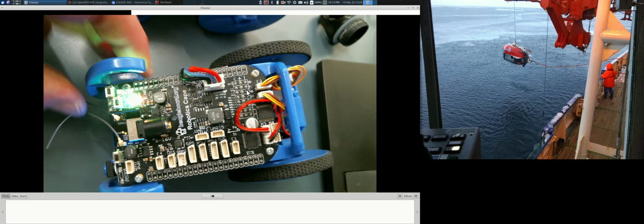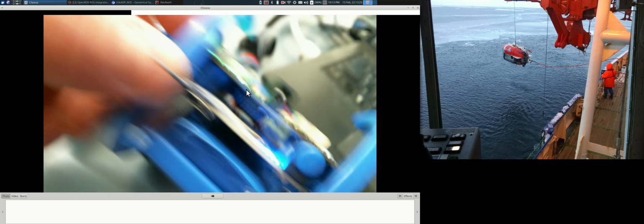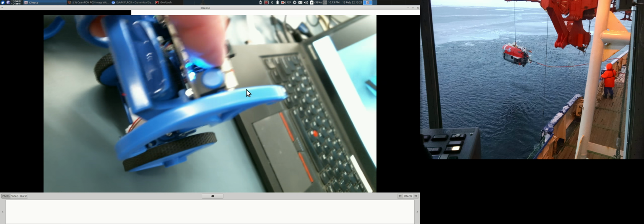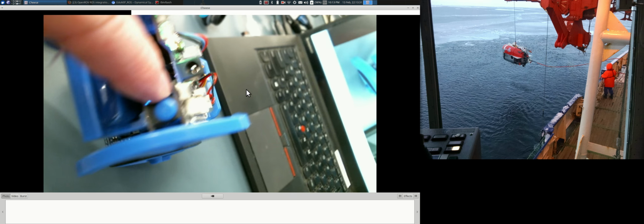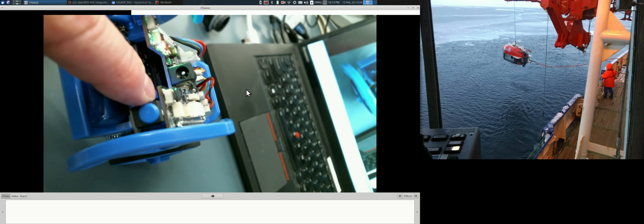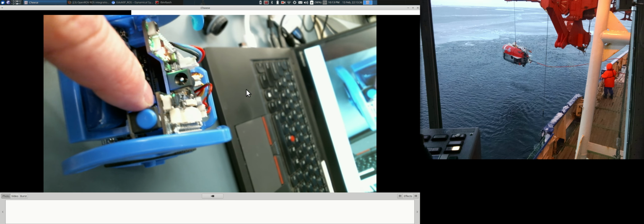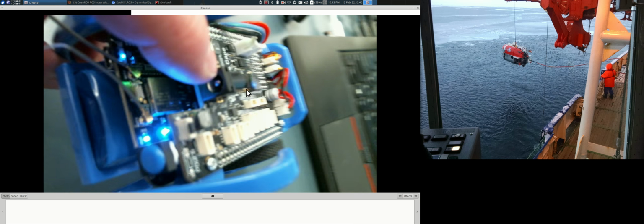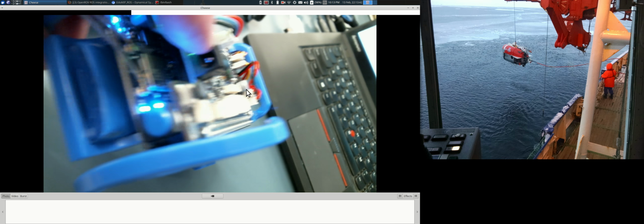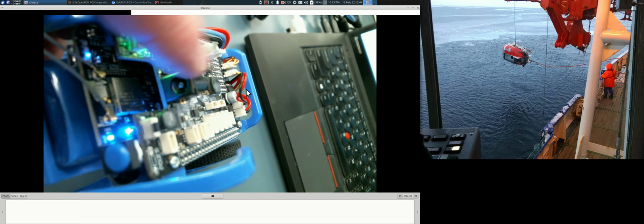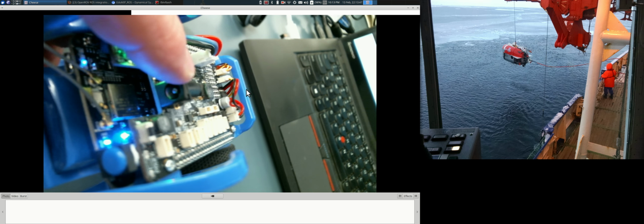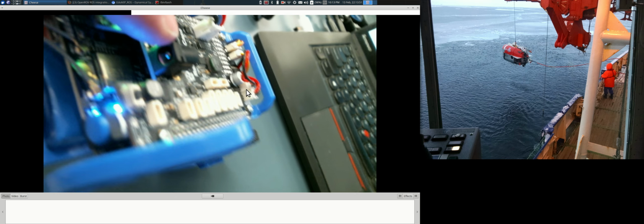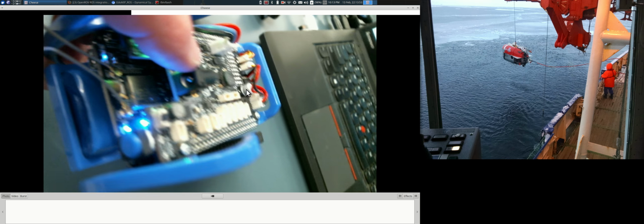And the one thing that I want to warn you is if you look at the older system, if you've got a pre-assembled one, there's 2 connectors for charging. This one that's plugged up down here is for 5-volt only charging, and if you plug your 9 or 12-volt adapter into it, then you'll smoke the board. And so up here is, unfortunately, very unfortunately, with the exact same size connector, this will accept, I think it's 6 to 16 volts. And the adapters that I have for you are 9-volt adapters for charging.